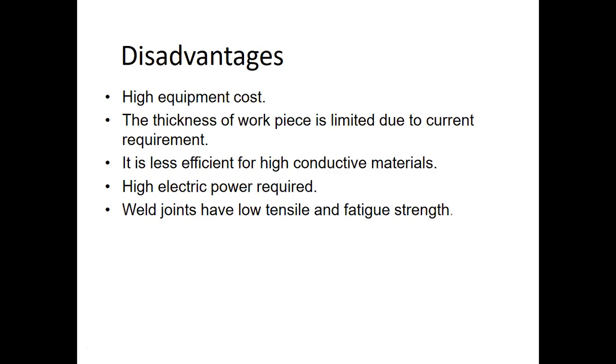High electric power is required for creation of that resistance. Weld joints have low tensile and fatigue strength, which is another disadvantage, because those spots act as stress concentrations, and therefore fatigue is also affected.